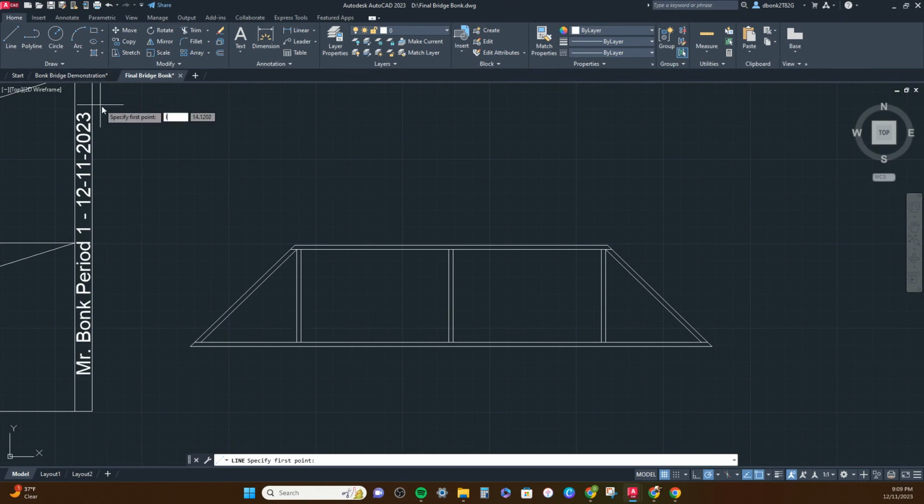In this case, you can hit L on the keyboard and hit enter, and that'll launch the line tool. Students could also just go here and draw a line diagonally. Here, you can do the same thing over here. I'm just using the escape key to finish that line. And now what I want to do is, if I were to draw just a regular line, I can get my indicator of this midpoint of this space vertically by just launching off of that midpoint of that diagonal line.